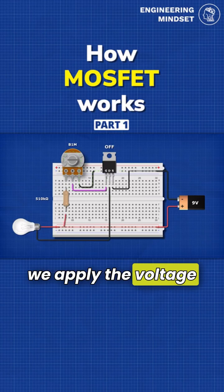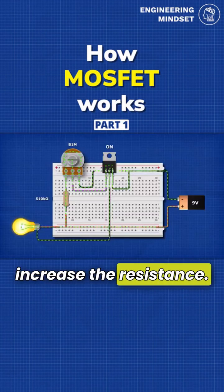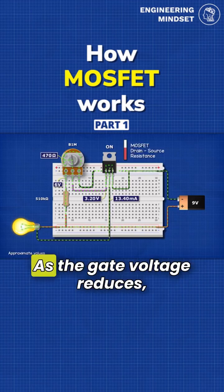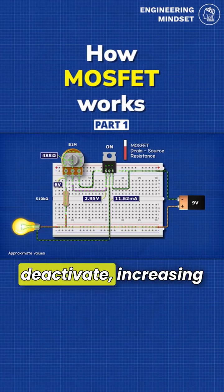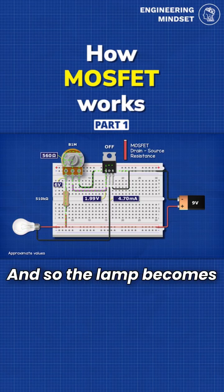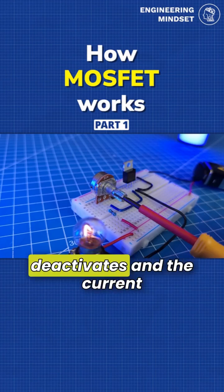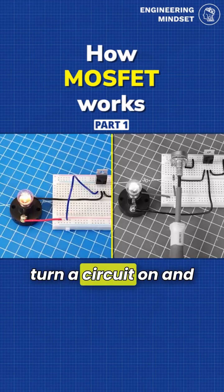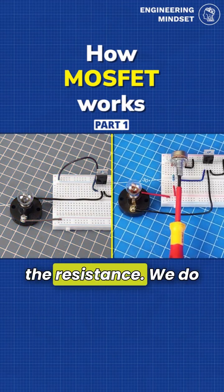If we apply the voltage again, we can rotate the potentiometer to increase the resistance. That reduces the voltage available at the gate. As the gate voltage reduces, the MOSFET begins to deactivate, increasing the resistance between the drain and source. And so the lamp becomes dimmer and dimmer until the MOSFET completely deactivates and the current is blocked. So we can turn a circuit on and off, or we can vary the gate voltage to vary the resistance.